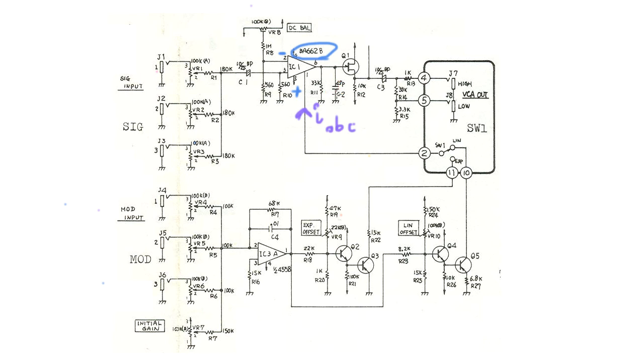Let's check out this 47 picofarad capacitor. Before we do any detailed analysis, let's just think about what it is at the extremes. At low frequencies, we can approximate the capacitor as an open circuit. So this is basically the assumed circuit that we've been analyzing. Well, what about at high frequencies?